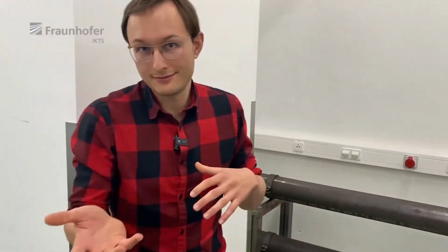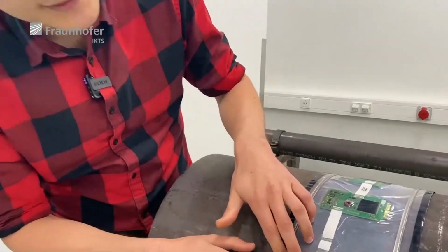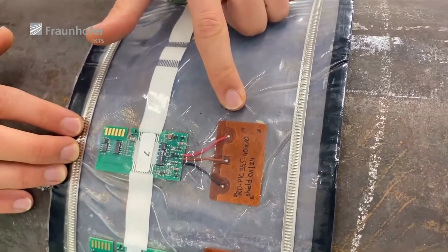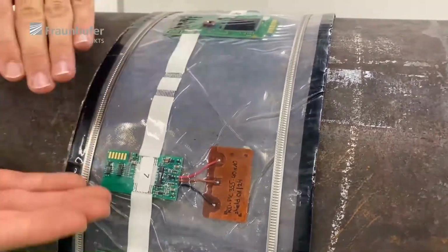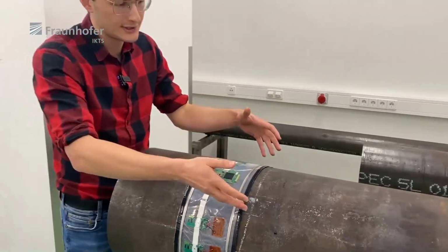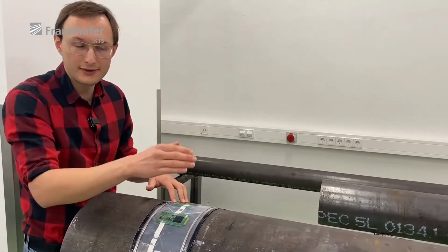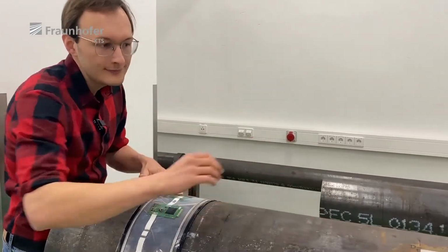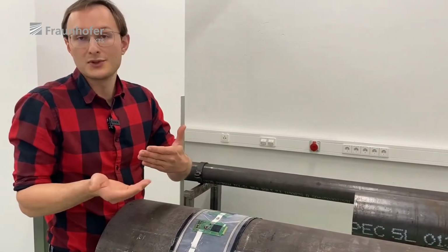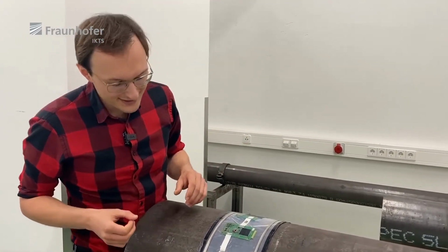Now, to do measurements using acoustic waves, we also need transducers, and you can see them here. That's a shear wave piezo transducer. It's tuned for a specific wavelength and the shear wave mode. So if it's underwater, the water would damp out-of-plane waves, so we use the shear wave mode, which also has the advantage of not dispersing, so the guys from analysis are happy about that.